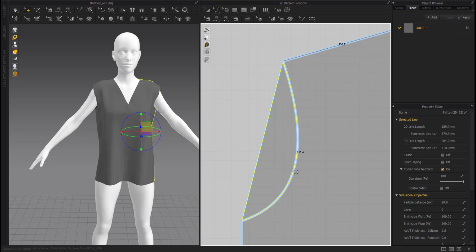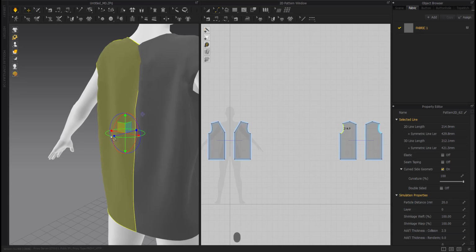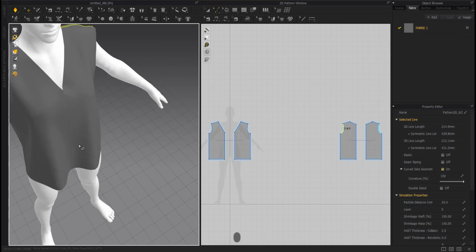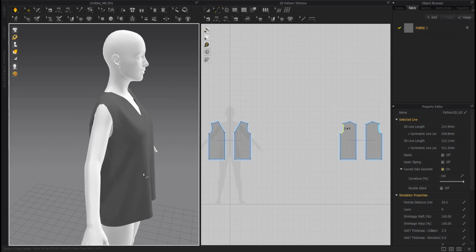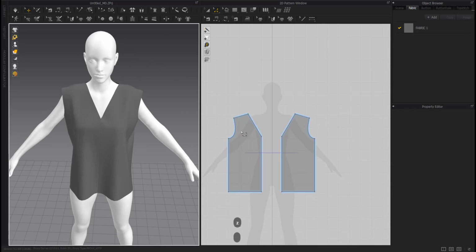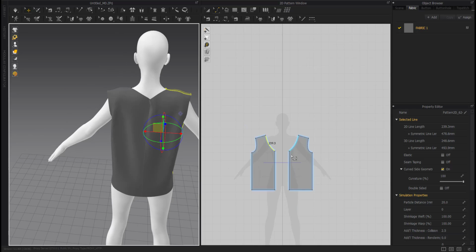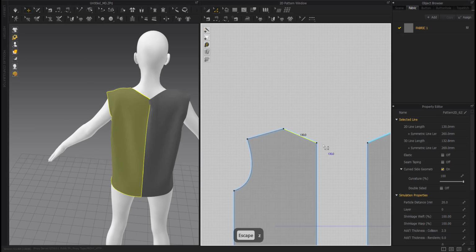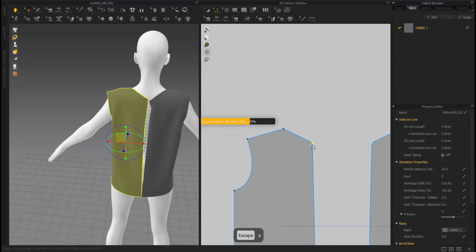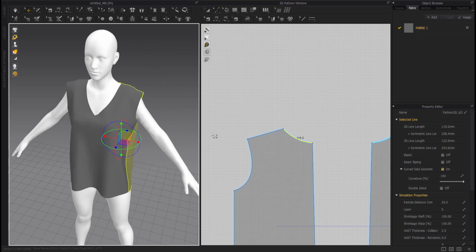Step 8. Add textures. Click on the Texture button in the top toolbar and choose a texture for the fabric. Adjust the texture scale and orientation as desired. Use the reference images to guide your texture settings, as different types of fabrics will have different surface textures. Step 9. Add details. To make the t-shirt look more realistic, you can add details such as pockets, buttons, logos, and tags. Use the reference images to guide your detail placement and sizing.